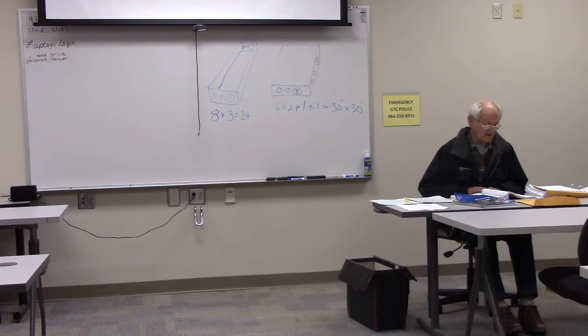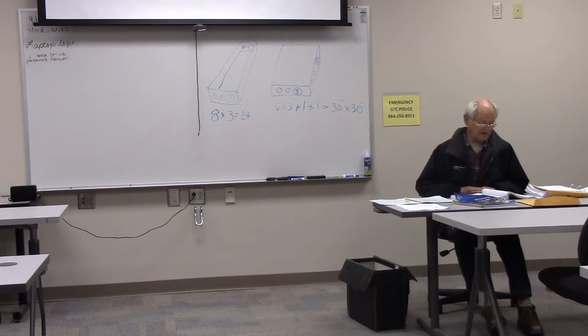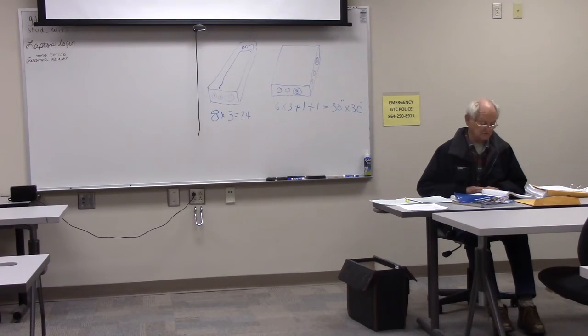Good job. A box installed under a roofed open porch is considered a damp location. Good. How many conductors must be deducted for each strap mounted device in a device box? 2. The capacity of an outlet box can be increased by using a raised cover.